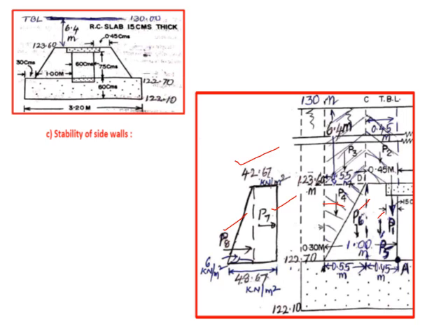So now you know that P1, P2, P3, P4, P5, P6 are making anti-clockwise moment about A. So they are entered in the resisting moment, whereas P7 and P8 are making clockwise moment. So therefore they are entered in the overturning moment. So this is the calculations part for the stability.